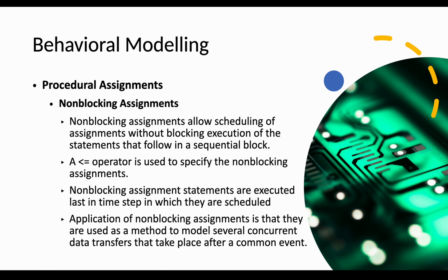The next one is non-blocking assignments. Non-blocking assignments allow scheduling of assignments without blocking execution of the statements that follow in a sequential block. A less than or equal to operator is used to specify the non-blocking assignments. Non-blocking assignment statements are executed last in the time step in which they are scheduled. An application of non-blocking assignment is that they are used as a method to model several concurrent data transfers that take place after a common event. We will discuss what an event is.